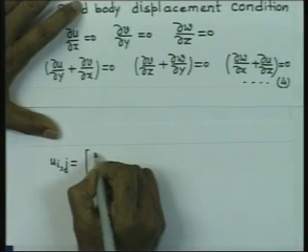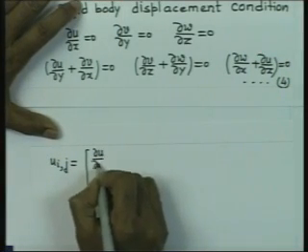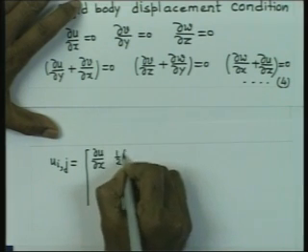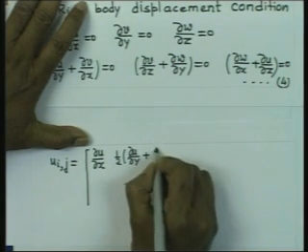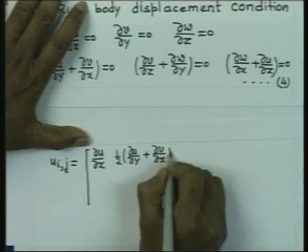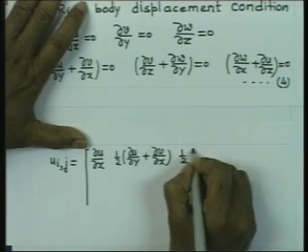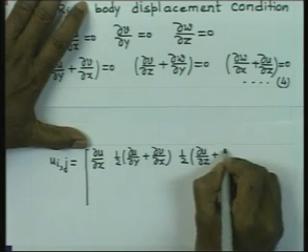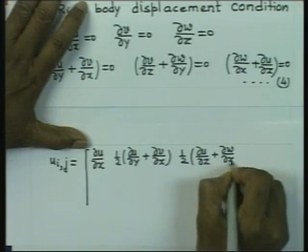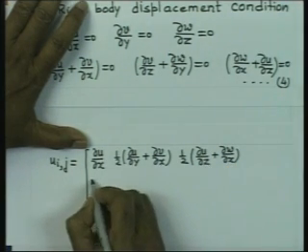So, the relative displacement tensor can now be rearranged like this: Uij is equal to, first row, delta U delta X, half of delta U delta Y plus delta V delta X, half of delta U delta Z plus delta W delta X. Then we have half